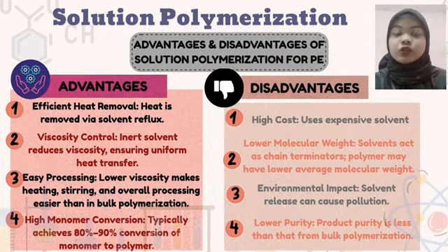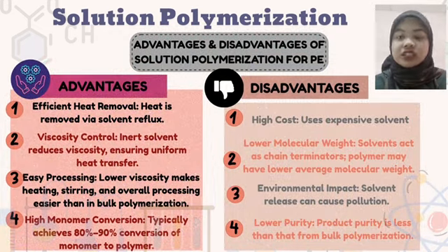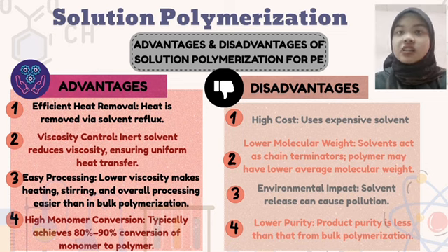Next, we go to advantages and disadvantages of solution polymerization for polyethylene. Advantages of solution polymerization. Firstly, efficient heat removal. Heat is efficiently removed through solvent reflux, preventing overheating.